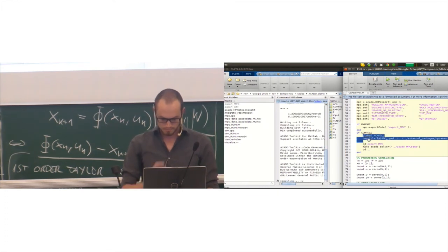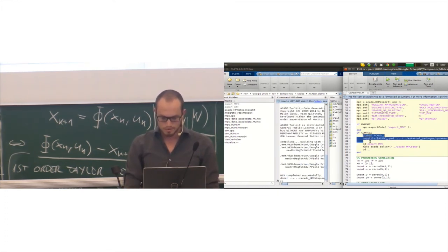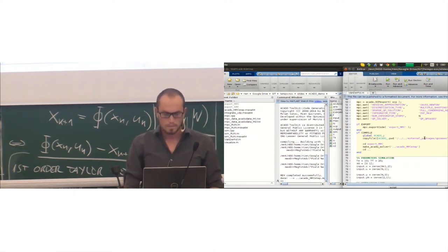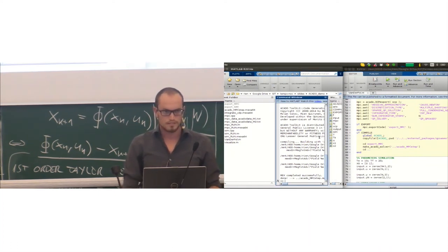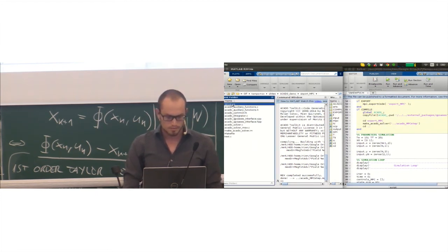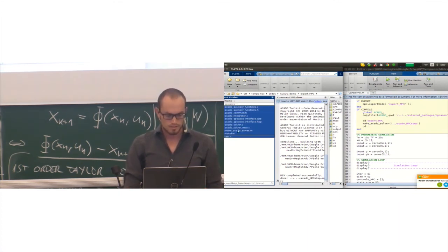The part that looks most complicated is actually just copying the qpOASES solver, as I'm too lazy to do this in front of you, and maybe failing at actually finding the qpOASES folder. You always have to copy your solver in there somehow, because you might be using qpDUNES and FORCES and so on, and we don't provide the solver together with ACADO, depending on which solver it actually is. So if you get some weird error, it's always a good idea to check if your solver is actually in the export MPC. If we check here, qpOASES, as we copied it in there, is in this folder together with a bunch of auto-generated files.